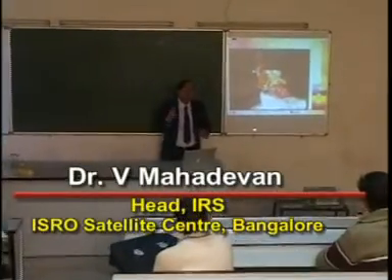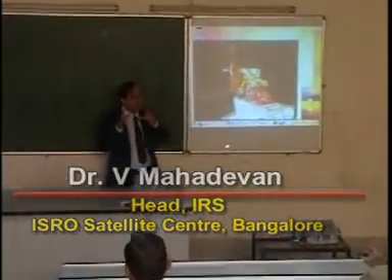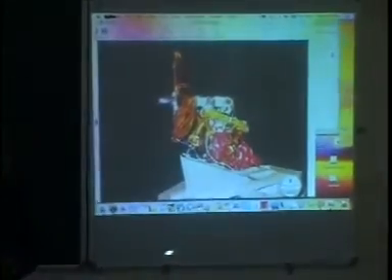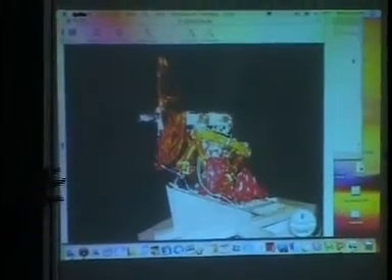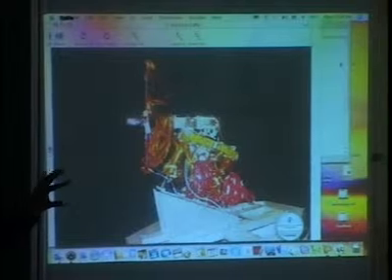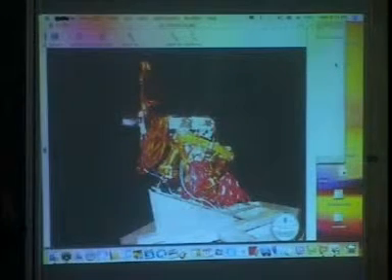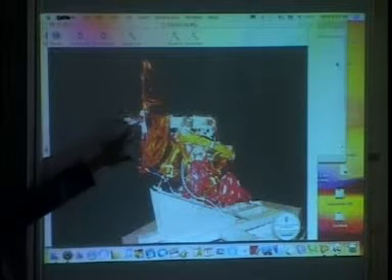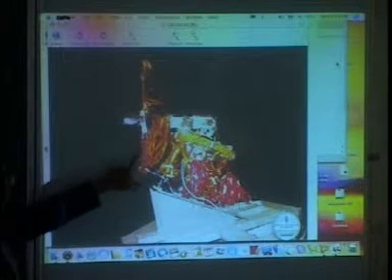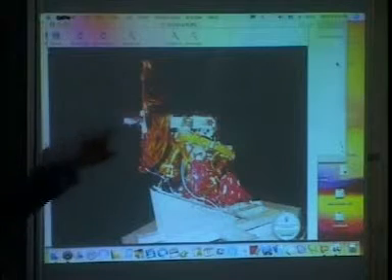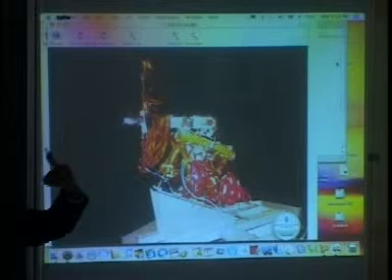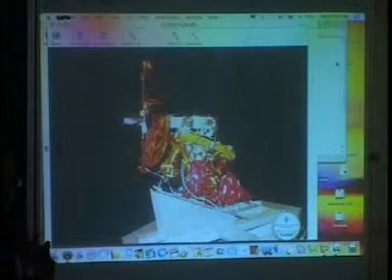Chandrayaan spacecraft, I was talking about the data transmission from the spacecraft to the ground. Some of this you have seen on the phased arrays earlier. Here this is not a phased array, it is a dual gimbal antenna. In the earlier case it was an electronic phased array antenna. This is a dual gimbal antenna where the antenna is fixed. This particular antenna produces the required beam, and that beam is rotated depending on the area of interest. It will point exactly to that station.